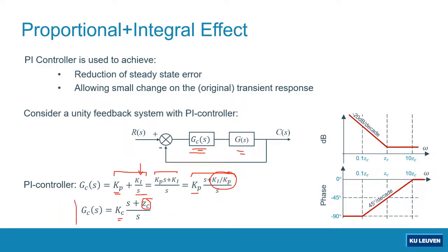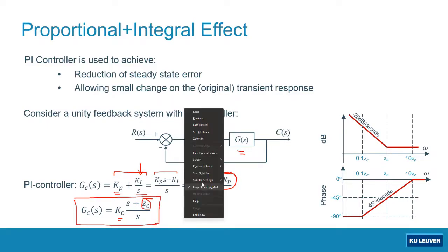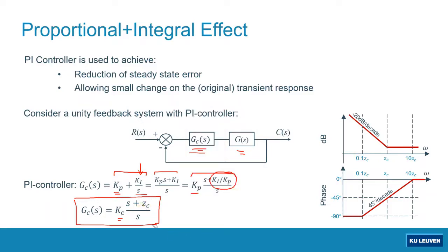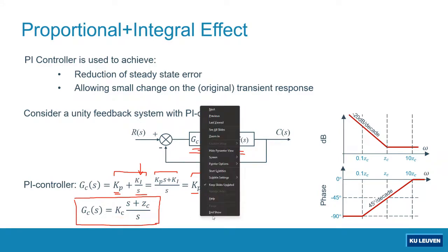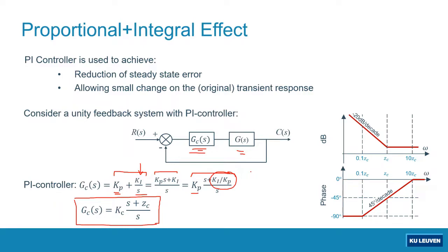This is now my new form of the PI controller in the form of a Laplace equation. So if you look at this, our PI controller appears as a function of Laplace, which means again it has a dynamic behavior by itself.